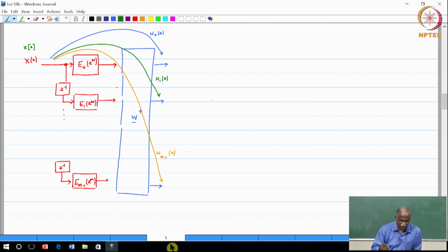We did a polyphase decomposition, H0(z) equals the summation over l equals 0 to M minus 1 of z to the power minus l times E_l(z to the power M), and then we applied the shifted versions, and we showed that what emerges is the following structure, with the polyphase components of H0 and then the IDFT matrix. This structure was derived in the last class.